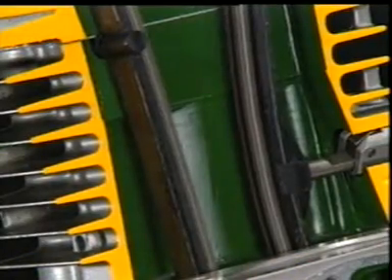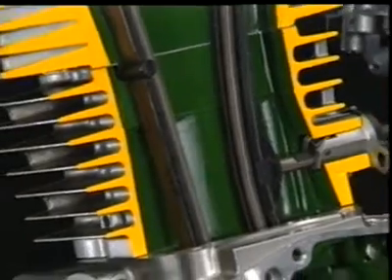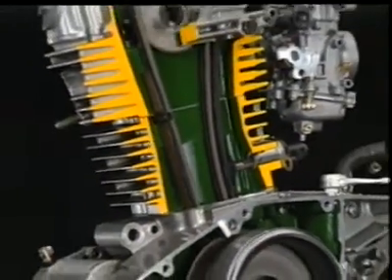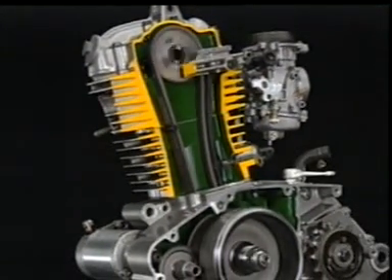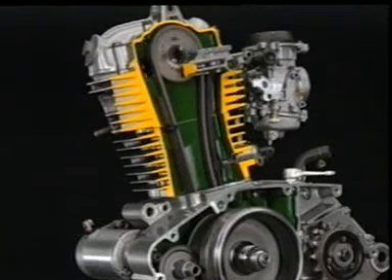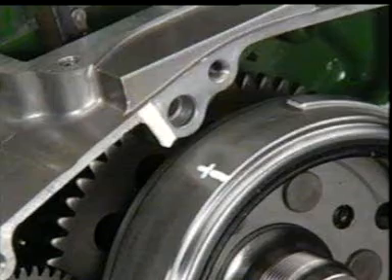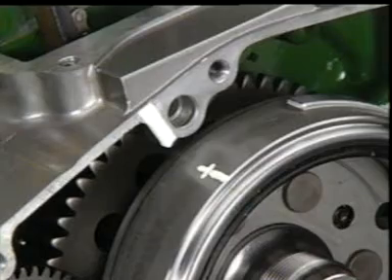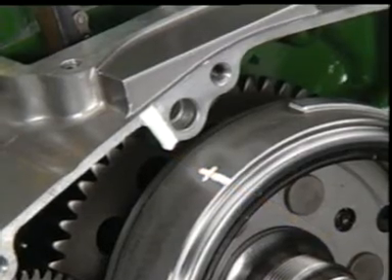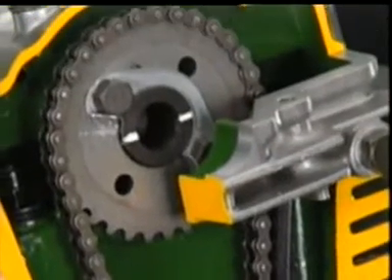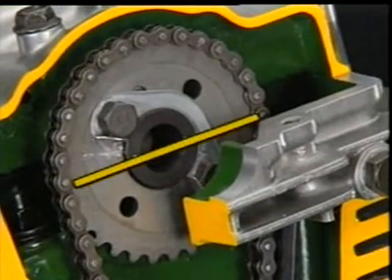The camshaft and crankshaft are connected by a chain that runs around sprockets on both shafts. The connection is designed so that the camshaft turns once for every 2 turns of the crankshaft. Whenever a 4-stroke engine is taken apart and reassembled, it is necessary to adjust the timing of the camshaft and crankshaft. That is to say, the valve timing.